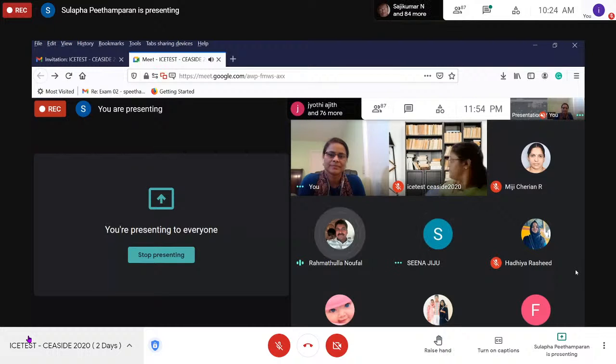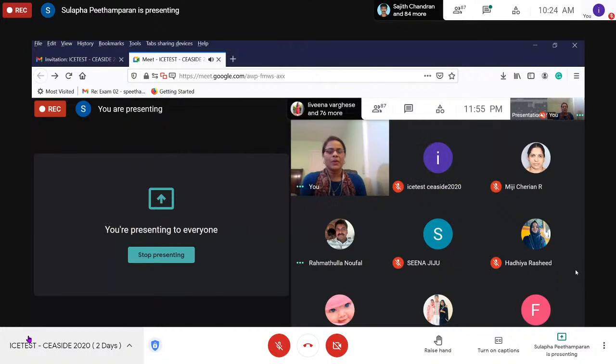So normal curing will affect the strength, no? Not at all. It doesn't affect the strength at all. It will remain the same. With water curing, depending upon if it is slag or things like that, you can prevent cracking if you are soaking it in water. Normal curing can be done. It is very similar to your Portland cement concrete, no difference.